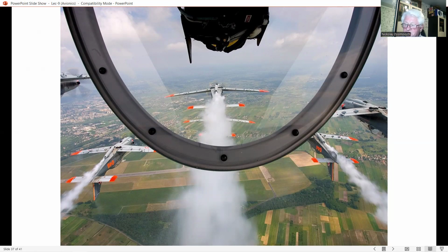In practice, however, gyro drift and errors in the necessary correction terms would cause a progressive build-up in the vertical error unless some means for monitoring the vertical error and applying correcting feedback were incorporated.